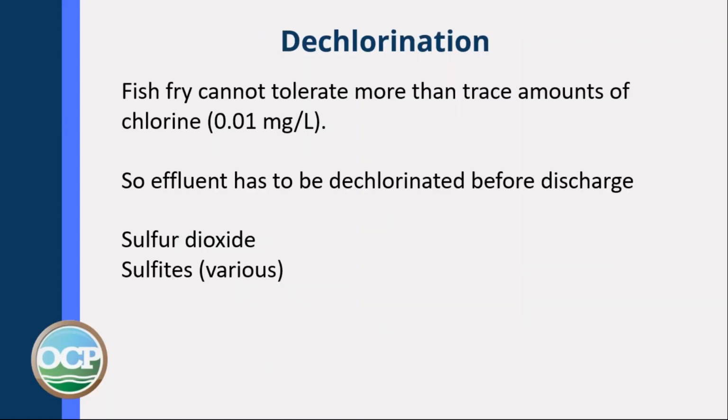For dechlorination, since fish fry cannot tolerate more than trace amounts of chlorine, the effluent has to be dechlorinated before discharge. Typical ways to dechlorinate it is with sulfur dioxide or sulfites.